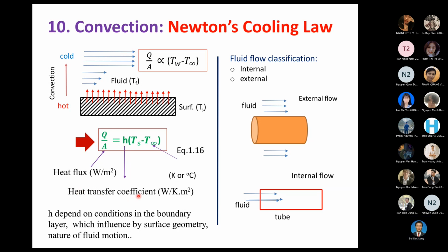This H depends on the condition of the boundary layer, which is influenced by the surface geometry, the nature of the fluid motion, or the mode of convection, whether natural convection or forced convection.